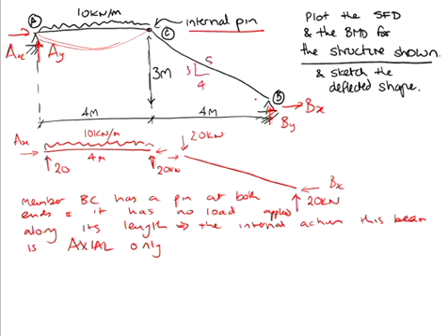So you can either consider it as a 3-4-5 triangle, or note that that angle in there is 36.86 degrees, and that's just through some trig. So if we know the value of By, which we do know, it's 20, we can very quickly work out the value of Bx.